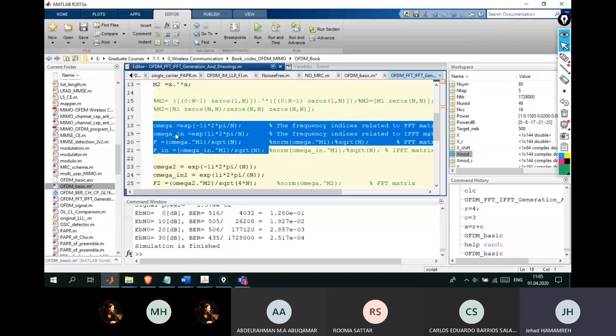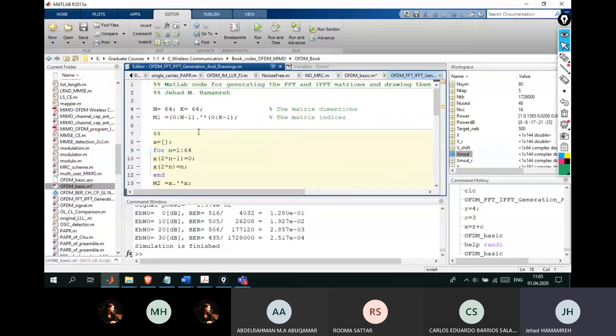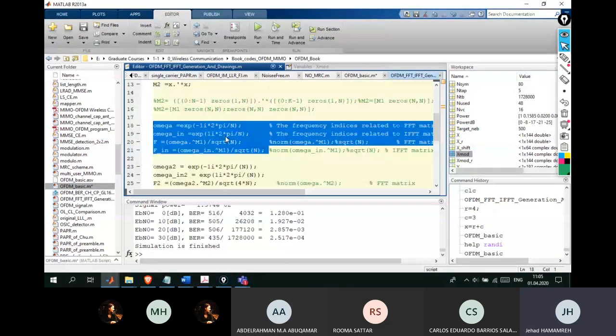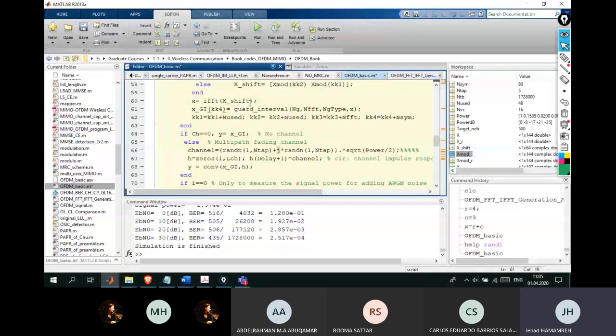I build it mathematically here, and this enables you to see the sine and cosine and sinc. But with this ready function you can never see the sine and cosine and sinc, because the input is data and the output is data. Sine and sinc are not related to the data. Sine and sinc, they are the carriers. And where are they? They are embedded in this function. If you want to see them, you must not use the ready function by MATLAB.